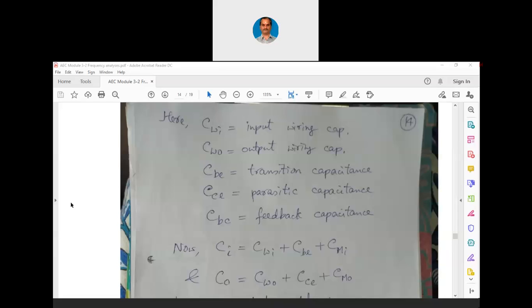When the amplified signal comes back to the base, the collector and the base are actually working 180 degrees out of phase. You already know that the common emitter model is going to produce a 180 degree phase shift between input and output. So when the amplified output is fed back to the base with 180 degree phase shift, at the input itself the signal gets cancelled to some extent. Let me annotate it and try to explain it in a better way.